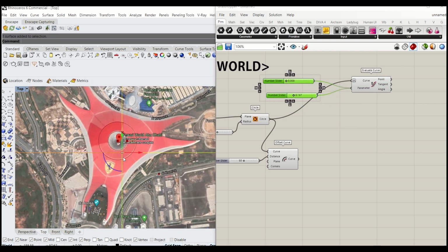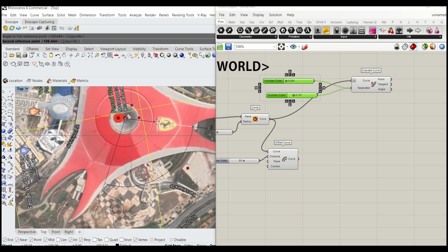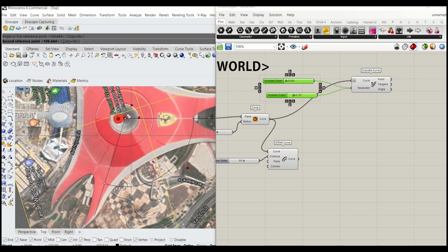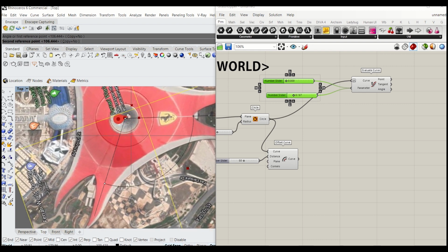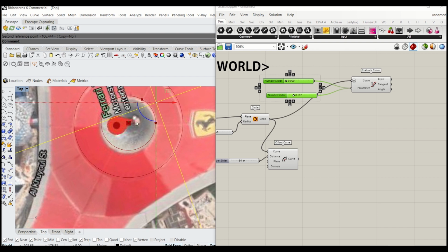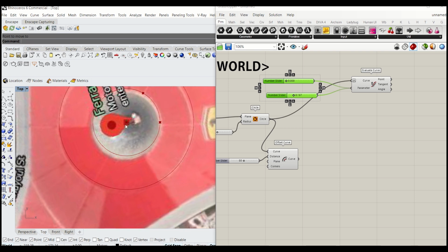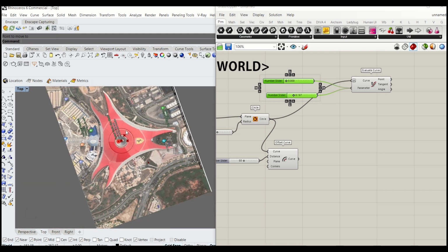And what we want to do next is rotate the background image so that we know the target section is placed at the right angle. So the seam there should go roughly around there. Okay, so that seam runs there and there. Slightly misplaced, I will move that. Okay, that looks about right, because you'll never get 100% accurate because the background itself isn't 100% orthogonal, because it's been taken from space. All right, so I'm going to lock this.